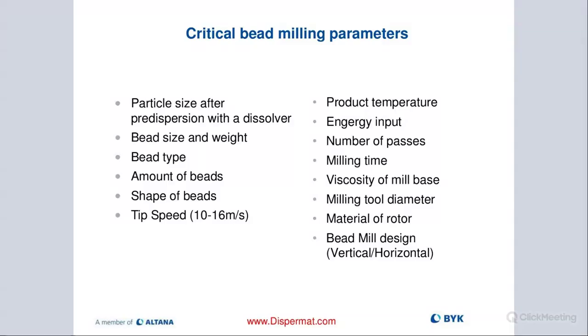Some bead suppliers offer samples that look really good under the microscope, and then when you buy your first lot, all of a sudden you see all sorts of shapes in these larger lots that they sneak in to keep the cost of the beads low. So very important: make sure you have high quality beads that are also perfectly spherical.